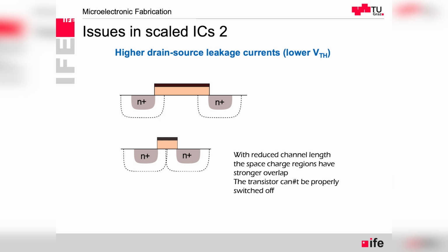But the FinFET transistors, that's another new modern device that is used from, I think, 22 nm technologies downwards. It's always FinFET. They wrap the channel around, so the gate is not only on top, but we have it on all three sides, and the control is much easier. So also we can access the regions deep under the channel much more easily and control them, thus reducing the leakage current.